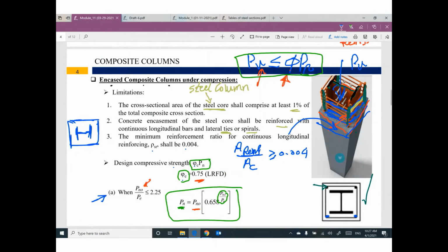After hardening, we will remove the formwork. So we have an advantage for this one, disadvantage for the other one. I'm sorry, vice versa. Formwork is not good because we need to wait 6 or 7 days to remove the formwork, and we need more workers and more hands.